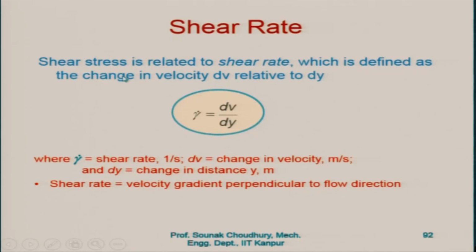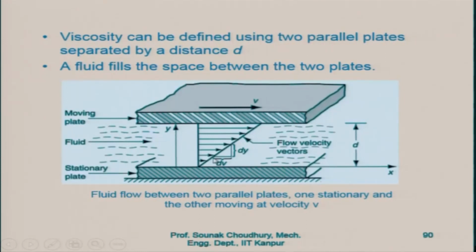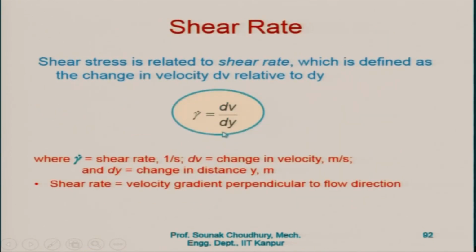Shear rate. Shear stress is related to shear rate, which is defined as the change in the velocity dV relative to the dy. So, if you see here, for example, dV here and dy here, this is the change in the velocity with respect to the distance. This is what we are saying, and this is the shear rate, because here the time will come into picture.